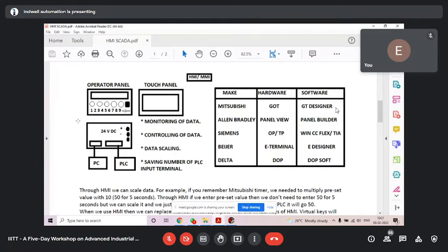Now behind any HMI, what do we have? Behind any HMI, we have first of all the power terminal. You can see power terminal: positive, negative, earth. Positive and negative will always be DC power supply, and always 24-volt DC. But I have seen some old small HMIs, not big ones, that had 5-volt DC also. But generally, HMI power supply will be 24-volt DC. Done? Okay.